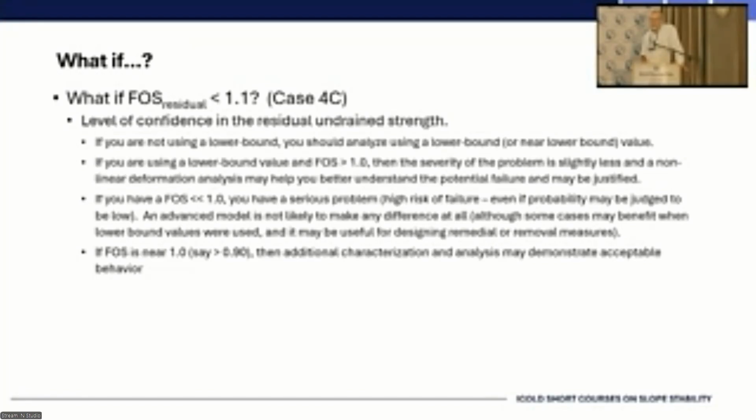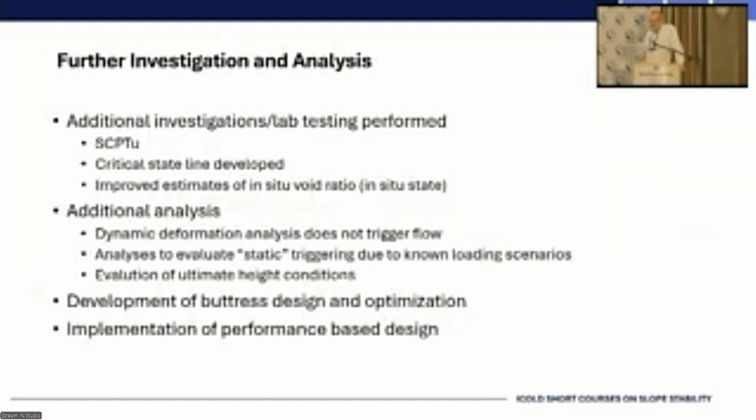If your factor of safety is less than 0.5, you probably need to do something. That could be curtailing activity, that could be initiating buttress construction. It might involve, depending on where you're at, relocation of people from the downstream hazard zone. Again, those are the really tough situations to be in, and some of you live in that area of reality. That may be your reality. I've been in cases before where I had to make judgment calls like that. It's no fun.